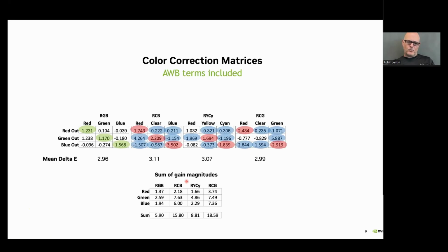So really, before I go on, actually, the white point preserving least squares to generate the CCMs gave me an average delta E of about 3 across all of them. So it's a fairly fair way to generate a CCM. Maybe not the best, but a fair way to do it. So I'm pretty happy about that.